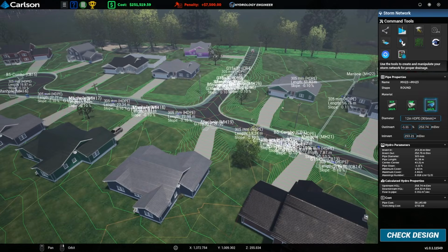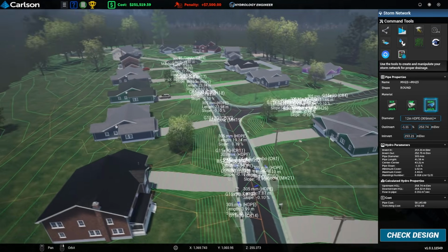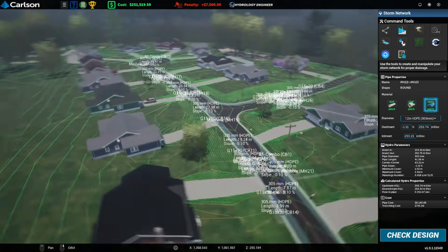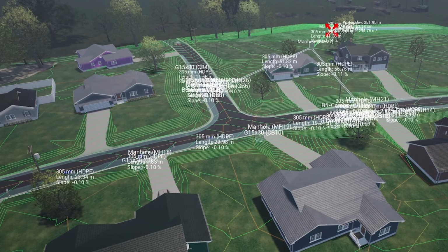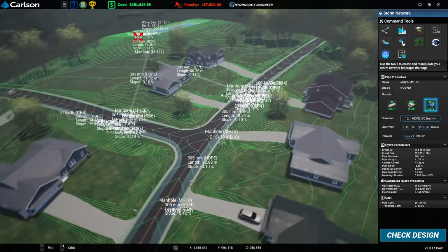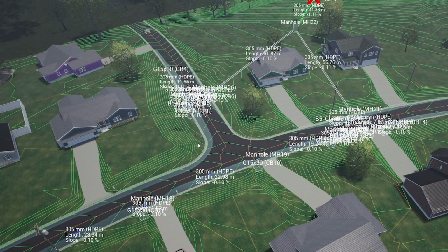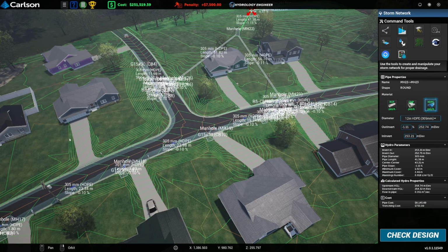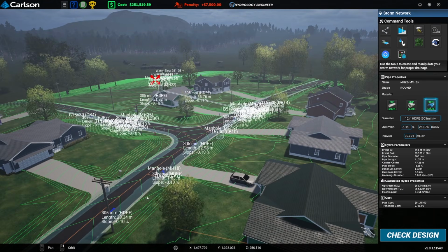Also worth noting, we generally add a percentage for climate change. So whatever this works out as, we would then add 30%, or more recently I think it's 40%, and that's an addition we add to account for climate change, because basically it's raining more and more. All the probability models are based on previous data. I think it started in the 1970s.